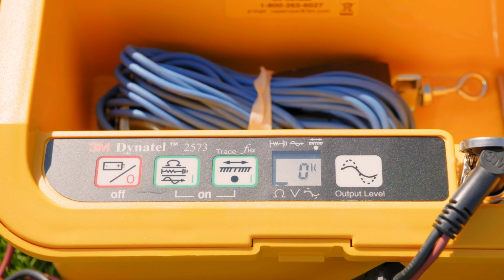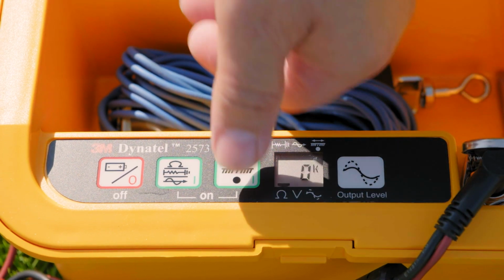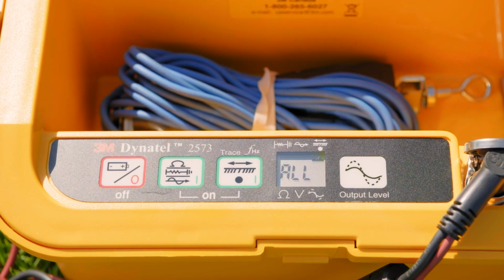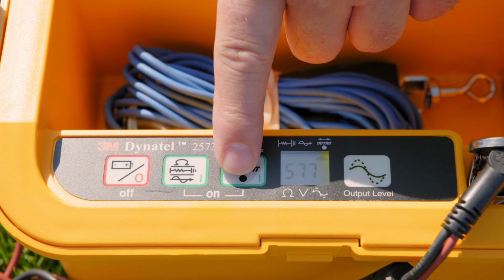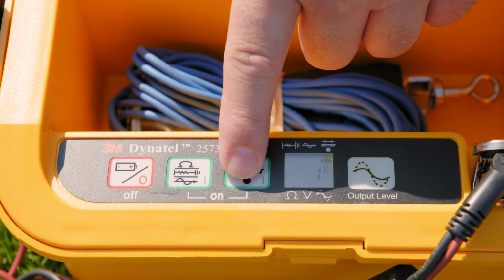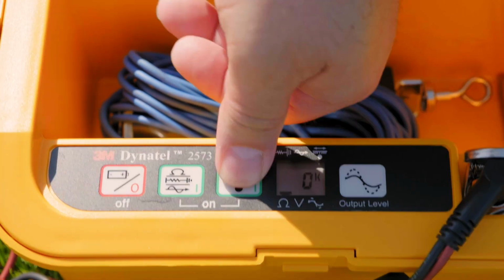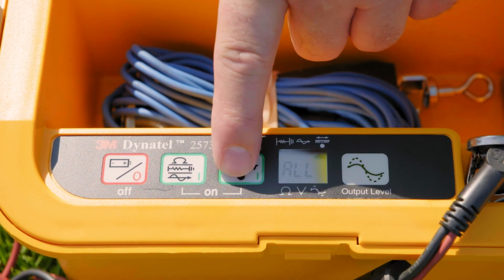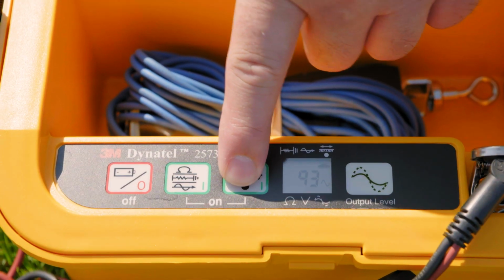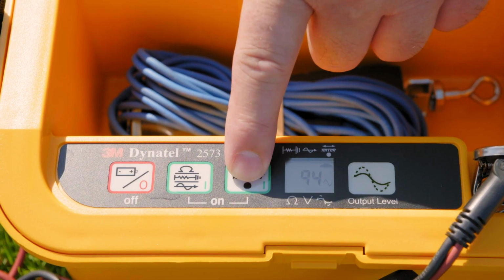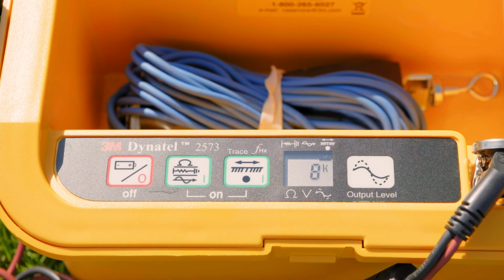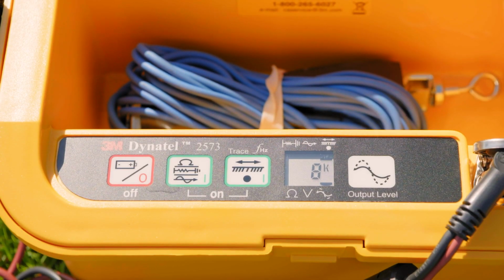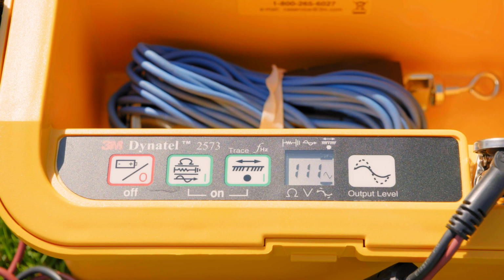In the previous example, we connected to a water pipe. When locating any type of pipe, it may be necessary to not measure resistance and just select 8 kHz or higher. If you locate tracer wire or other types of cables, you should always select the lowest frequency applicable to the resistance of the signal path. Using the lowest frequency is a good practice because the lower the frequency, the less chance of bleed over signal to adjacent facilities.